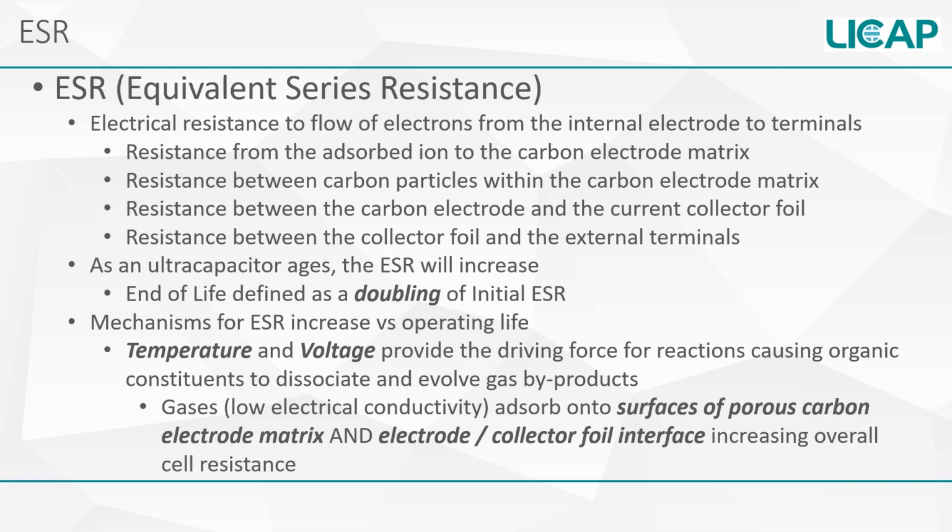As stated in the previous slide, the temperature and voltage driven reactions cause gas byproducts that are adsorbed onto the surface of the porous carbon electrode, as well as the interface between the bulk electrode and the current collector foil. These gases have low electrical conductivity, or high electrical resistivity, thus increasing overall cell ESR.